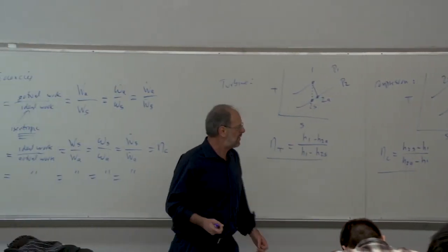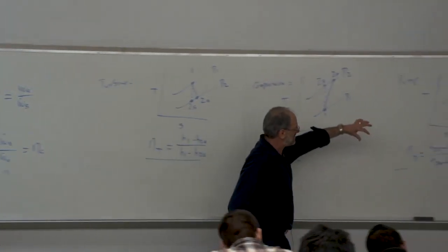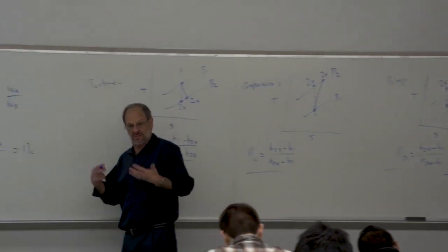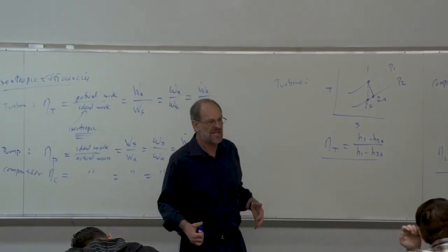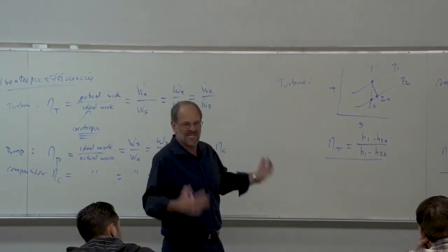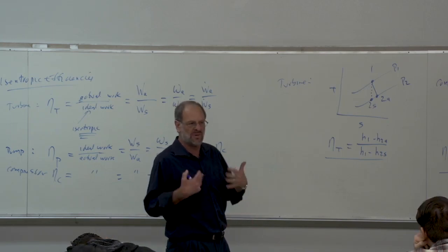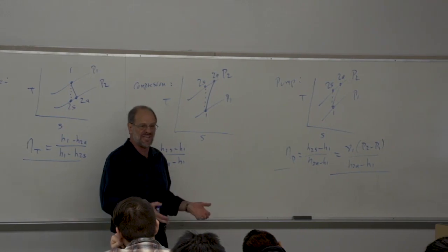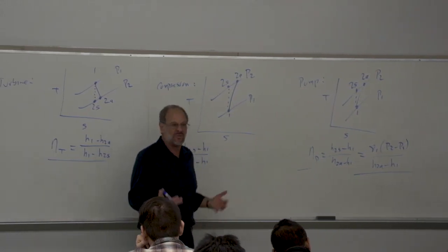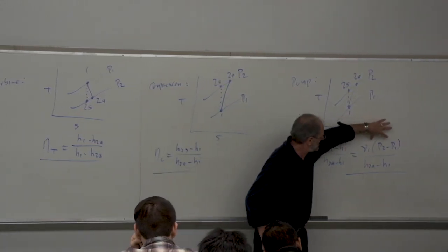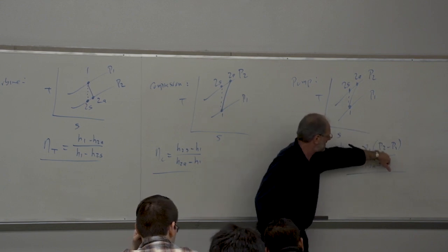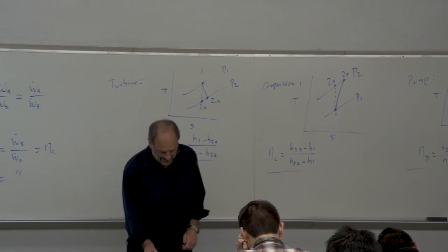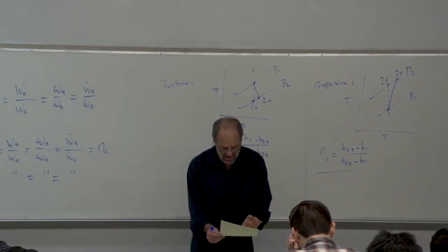Now, by the way, we wouldn't have to use this version if we had good compressed liquid data in our textbook, right, in our table A7 for water, for instance. But again, table A7 starts at such a high pressure, it becomes practically useless to us. So if we want to solve a problem involving a liquid, we just don't have good liquid data. What other choice do we have but to use this version? Because this is data we can just look up in the saturation tables. Okay. So anyway, let me now move on.